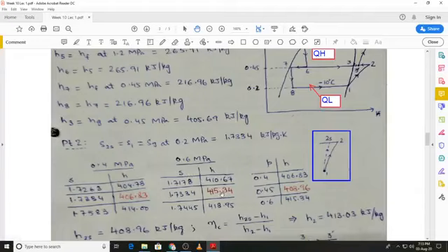And that was the first interpolation, and now we will have to interpolate again by using the pressures. So we now know that if we keep the entropy constant at 1.7334 kilojoules per kilogram per Kelvin, at 0.4 megapascals the enthalpy is 406.83 kilojoules per kilogram, and at 0.6 megapascals the enthalpy is 415.34 kilojoules per kilogram. So we can easily interpolate to find out the enthalpy at 0.45 megapascals, which comes out to be 408.96 kilojoules per kilogram.